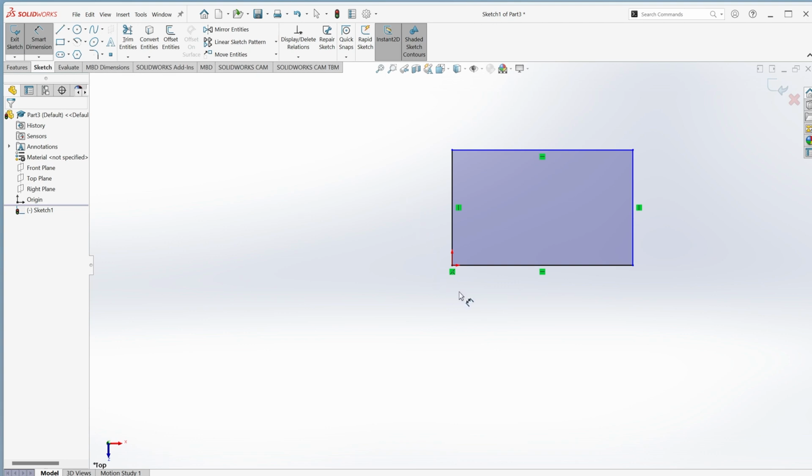Just as a brief outline, any lines in the sketch which are colored black are constrained. Any lines in a sketch which are blue, like these two, are not constrained. Initially, when you're first starting out with SolidWorks, this doesn't really seem to matter. As you get more involved, however, you'll find that it's important to fully define your sketch before you start doing the next thing with it.